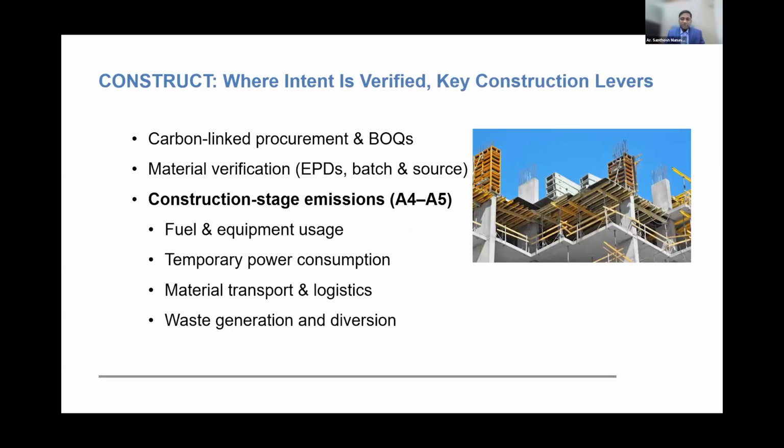So construction is where net zero intent is tested against reality. Carbon targets must be embedded into procurements and BOQs. Materials delivered on site need to be verified against the EPDs, to check whether the contractor is procuring the same, so the on-site teams can verify that. It's recommended to do audits on site. And most importantly, the project must capture as-built carbon data, replacing assumptions.